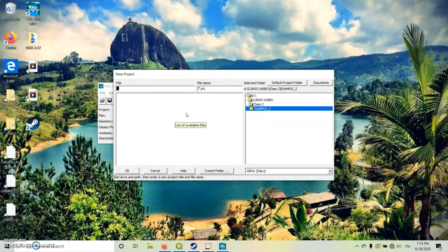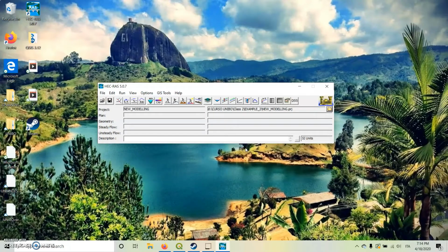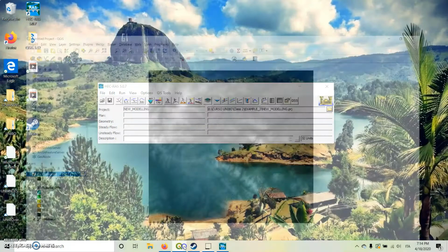Here, so new modeling. Okay. And I will use the same shapes as Castellarini. So in here we need the raster file of tutorial DEM, but in HEC-RAS you have to use the raster as a TIFF file. So for that we are going to use QGIS again.